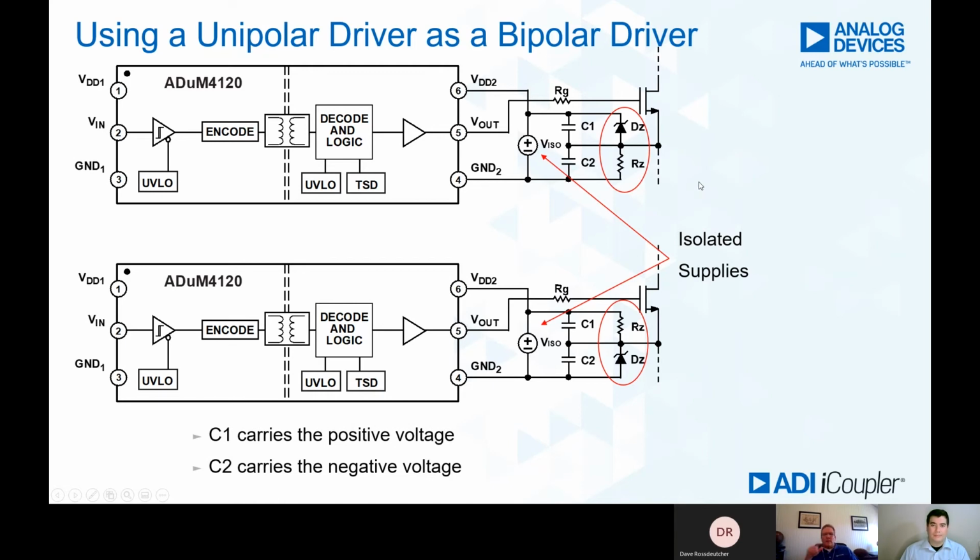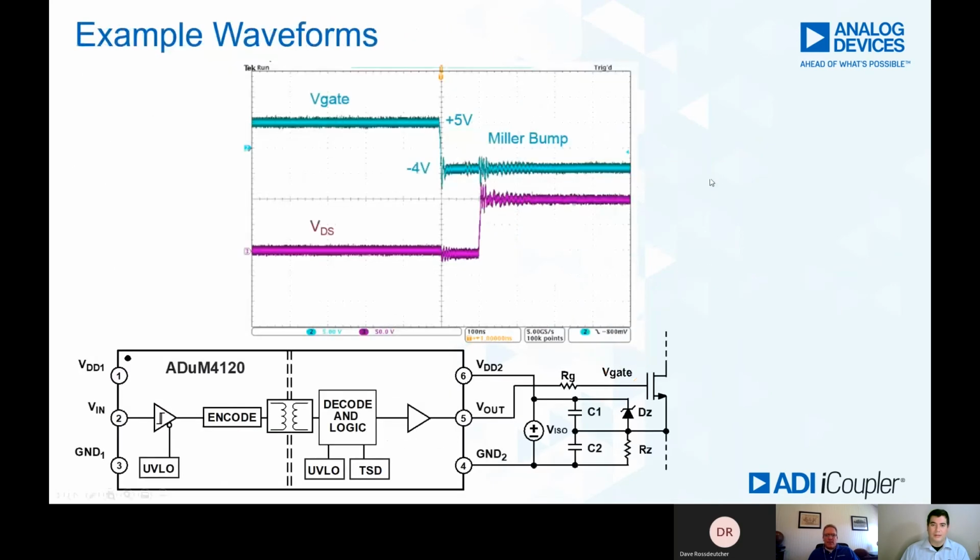Okay. And it's probably, like a silicon carbide gate drive level of +15, -4, depending on how much tolerance there is in those gate drive levels, for the tighter tolerance one you'd want the Zener regulator on. Yep, exactly. Okay. Any particular concerns when selecting the specific Zener diode used? You usually want the lowest quiescent current in order to have lower losses.